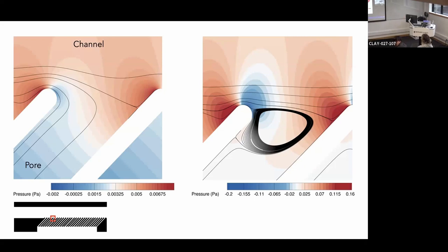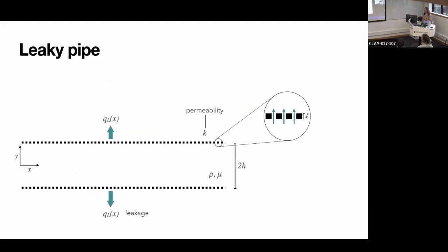If there's any rotation in the flow, is that going to segregate your particle sizes between the wall and the interior of the flow? Yeah, great question. Let me just put up my channel. So we have sort of assumed that the particles are uniformly distributed. And the question is, that's not necessarily the case, right? So there are certainly cases in channels where, owing to shear effects, owing to inertial segregation, owing to rotational effects, particles can be sorted by size or can congregate at different parts of the channel.